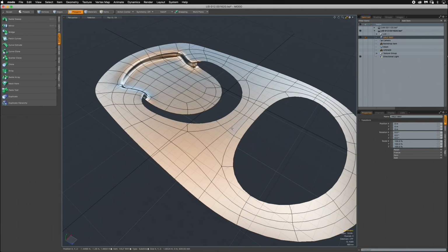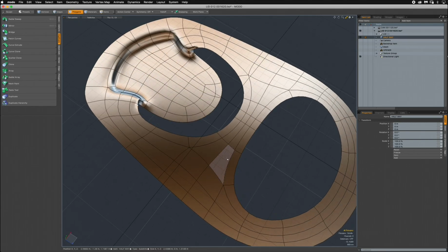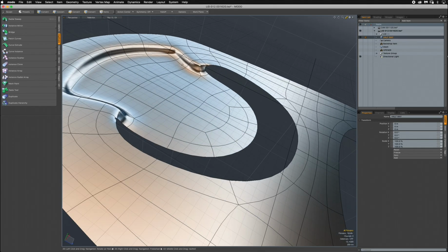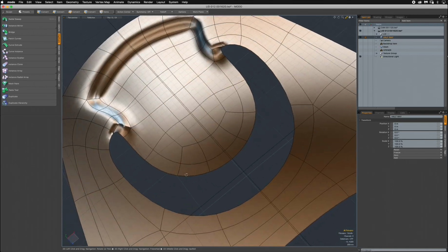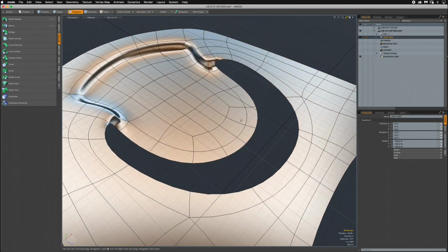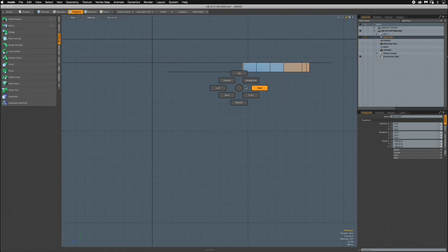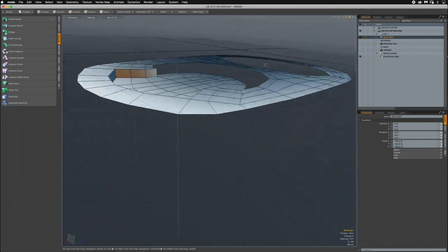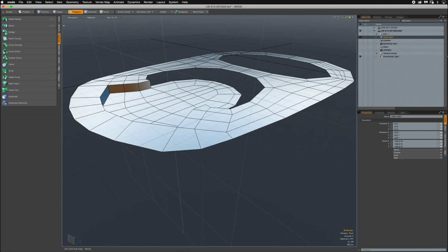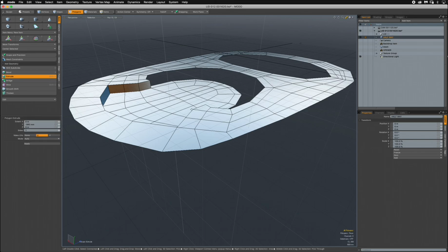So now that we have that done, if you move this to an angle and click tab, you're gonna see that you just get this material. It has the same feel that you have from that model that we just built. Okay, with that said, let's go back to tab. Let's go into right view. Actually, even a perspective view, so you see a little bit better. And we go to basics here, extrude. Click on this, move it down a little bit.